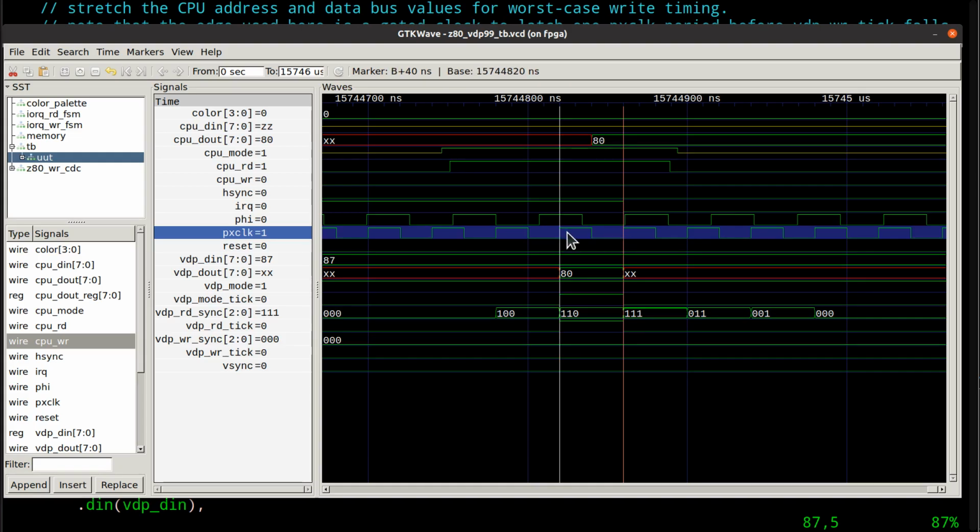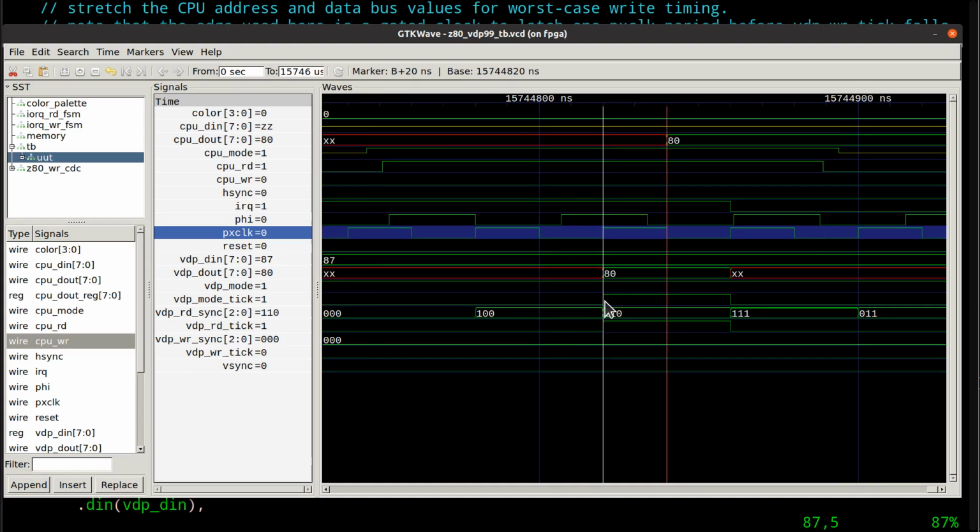It's this many nanoseconds long. It's 40 nanos for the whole thing, so this is 20 nanos in here. I know that the spec of the FPGA, it would be hard to buy an FPGA that cannot have the value of its latches ready and stable within 20 nanos. That's a long time in FPGA land. So I know I'll be stable.